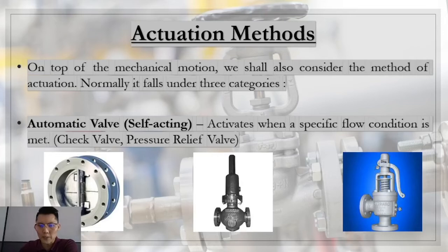And in the middle, this is a pressure regulator. How this pressure regulator works, in detailed construction, we will cover in another topic as well. But in this chamber, there's a spring located here. How can we regulate or adjust the spring? It performs the control of the pressure in this cavity. Same as this one, you can see this is a spring pushing down the cylinder. Imagine pressure from the bottom to the top. When the force from the spring is higher than the inlet pressure, the valve will remain closed. If the pressure is higher than the force of the spring, it pushes the spring up, and the fluid will relieve through this other flange type